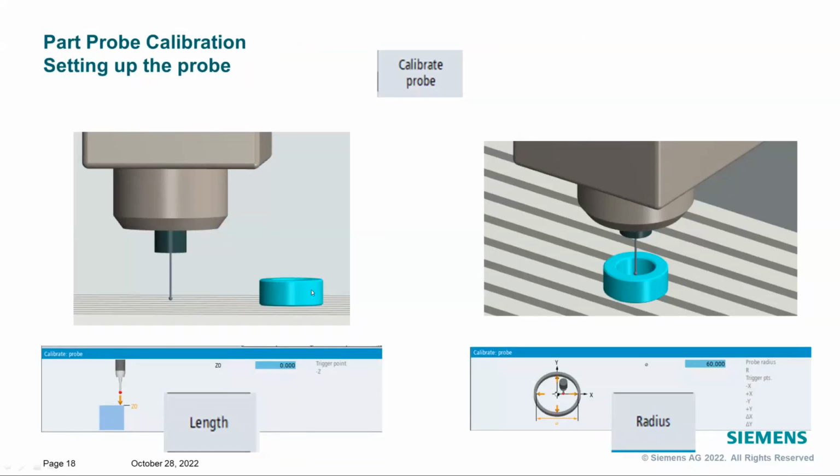They gave us a ring gauge that we can use for calibration purposes. The other thing is the machine zero of these machines is the center of the table and the top of the table. So when I go to calibrate in Z, I'm going to make sure I don't have any work coordinate loading. And with that, I'm going to come down and I'm going to datum it off the table, which will be location 0. As far as the ring gauge is concerned, you'll see there's a little print in there. It's a diameter of 60, so we're going to use that to calibrate up the probe.